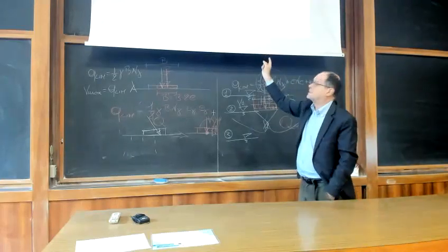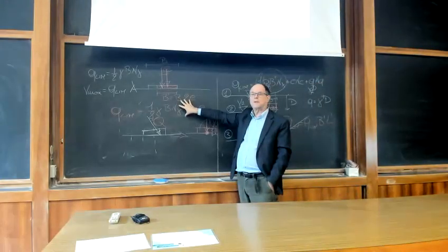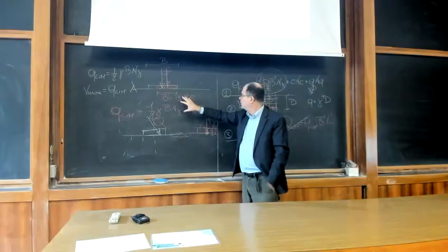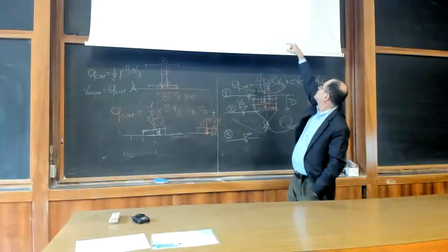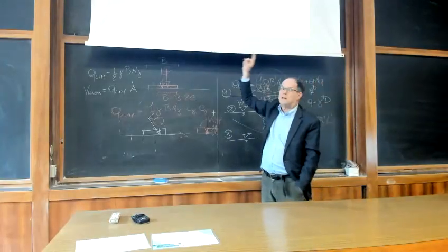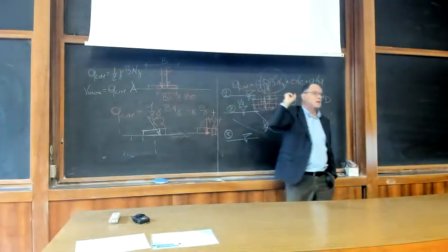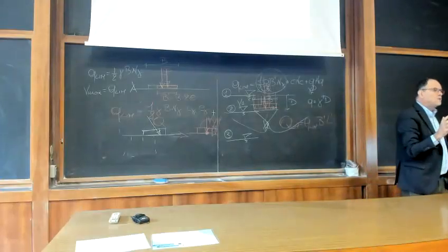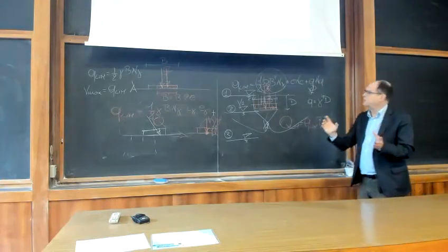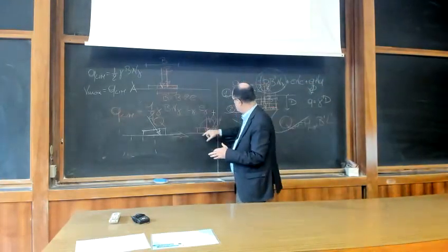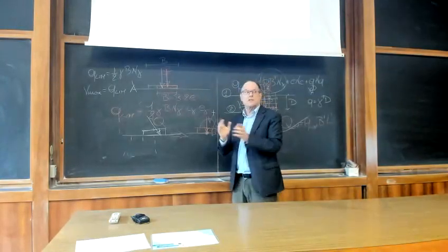And this expression, where does it come from? Exactly from the concept of the effective breadth. Nothing new. If you plot this thing, which I have showed you, in these terms, you can turn it around and show that the concept of effective breadth plots like this in this interaction diagram. So you can use the two deviatoric components, horizontal and overturning moments, deviatoric from the vertical loading components, in the same way.